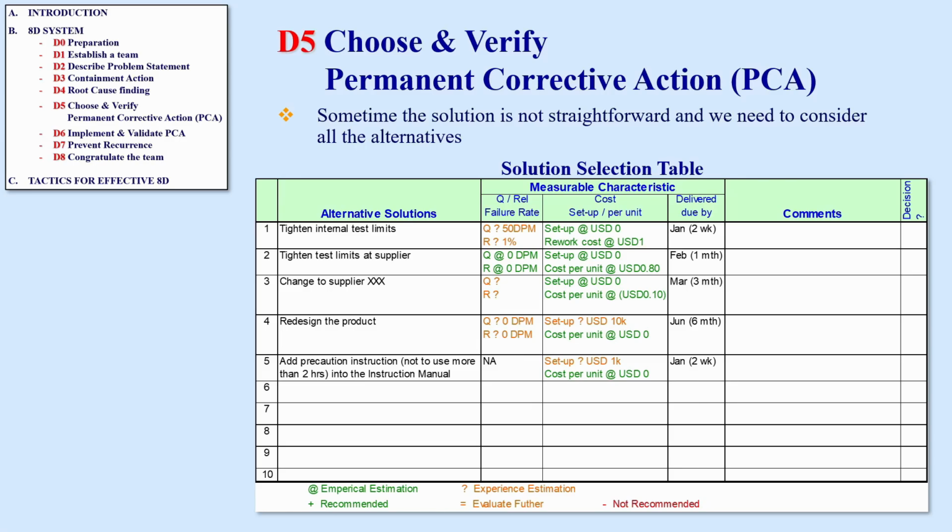The spec limit is a bit too wide. Though the capacitance for the selected component is within ±5% of the nominal value, which is the limit per industrial standard, we might still observe a certain failure rate. This happens while the capacitance value is near the spec limit.